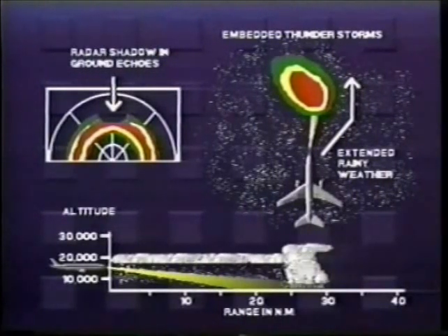see this radar presentation. Now, when you approach the embedded thunderstorm, you will see the ground returns become shadowed and immediately make the decision to fly away from that area. Under these weather conditions, always fly toward the displayed ground returns. Although this procedure works well in extended rainy conditions, we cannot overemphasize that weather radar should be used for weather avoidance, not penetration.